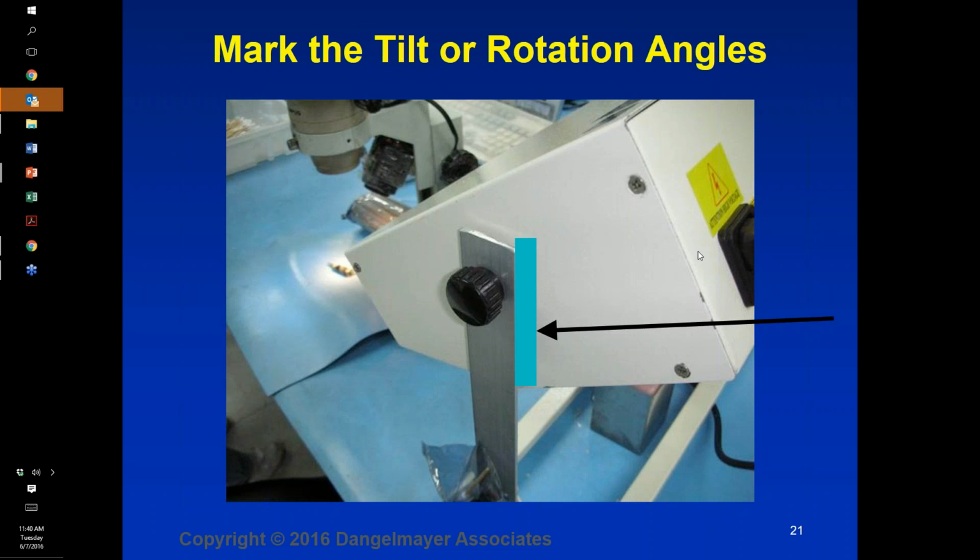Another good question, Arnie. Can an ionizer be beneficial in a low humidity situation? Oh, absolutely. In fact, it's one of the reasons why high humidity really isn't required in a well-designed ESD control program.